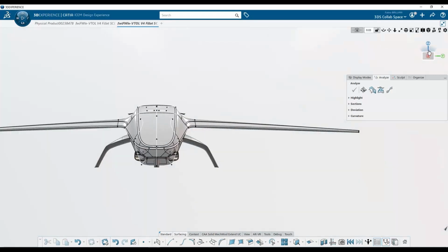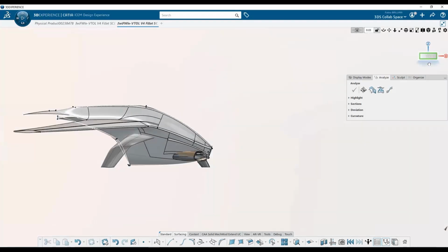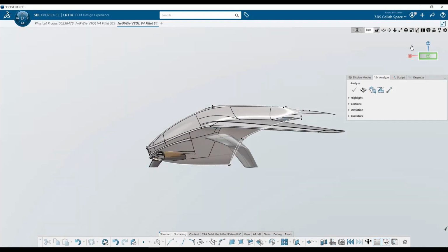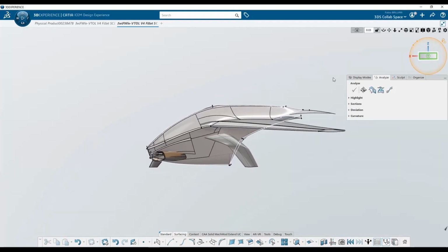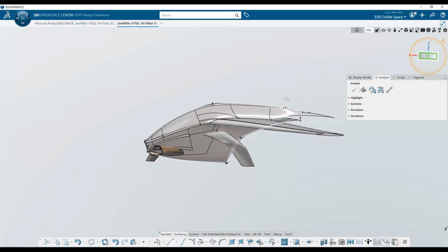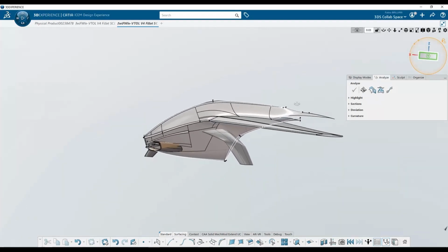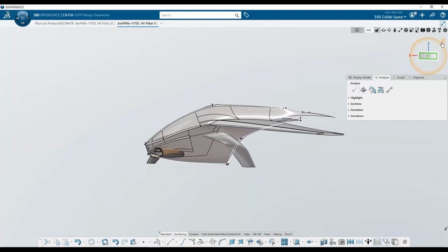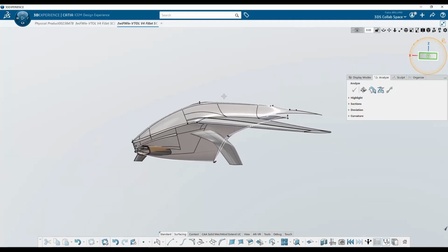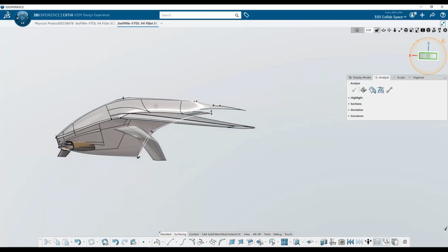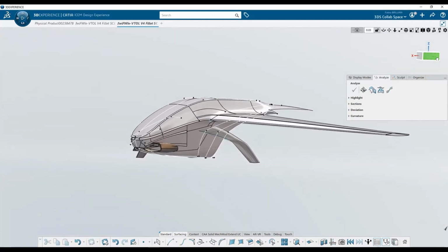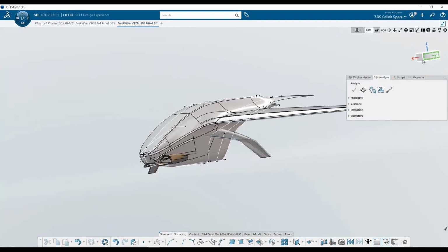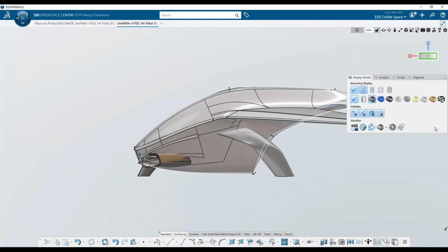This is the place where you can easily move from standard view, switch from the right, left, top, bottom view. By clicking on the orange circle of the VNav, we are able to manually rotate, but also lock the plane view, allowing precision during sculpting phases, and also lock the rotation, only allowing the pan. Those tools are really helpful for focusing on the sculpt. You can also define the working plane by clicking the middle mouse button on top of the VNav, and you have this dashed highlight, providing the user feedback related to the active working plane.